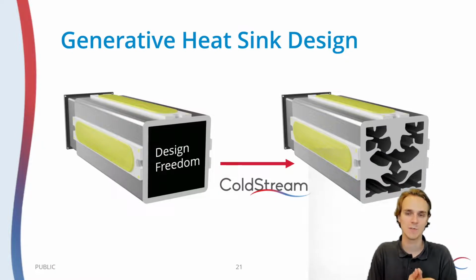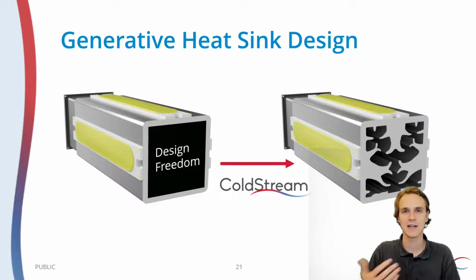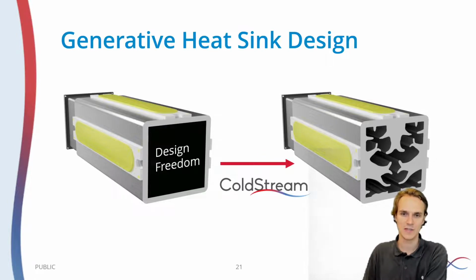And then when you submit the case, ColdStream, as you saw in the video, will compare hundreds of different designs to each other, each one of those backed with a CFD performance evaluation, so a full simulation like we saw with the LED fixture I just showed you, and eventually reach a global optimum of the best performing design. So you just have to specify where do I have space for the heatsink, and ColdStream will find the most optimal one, like you see right here. And so for context, this was an LED fixture that had LED strips on 3 sides, and therefore you see the design as such.